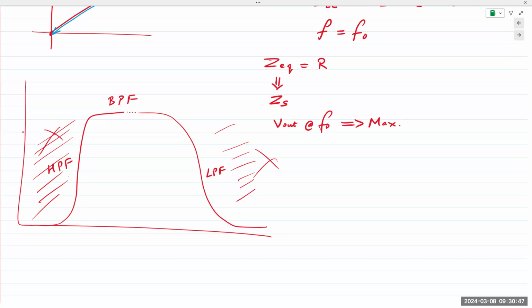Now, if you had your FL and FH here, you have a band of frequencies in the middle that's allowed to pass through. What if you switch the location of both of these filters? What do you get? If you take these two FL and FH cutoff frequencies, you switch the locations. They would intersect somewhere like this.